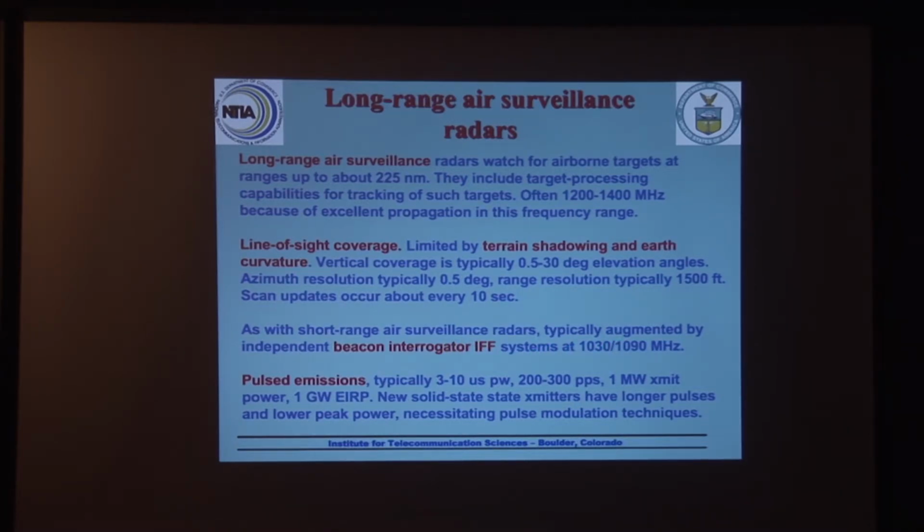a given area. By the way, one of the reasons for IFF is not just so you can spot or try to get some assistance with spotting bad guys who either are not responding to the beacon at all and are being seen by the radar, or who can't come back with the right codes, but also so that if you see a response back from an interrogation and the response says, "Hey, I'm a friendly person," you don't accidentally shoot at them. Pilots really appreciate that feature, especially with the new air defense systems that basically really don't miss anymore, movie scenes notwithstanding.